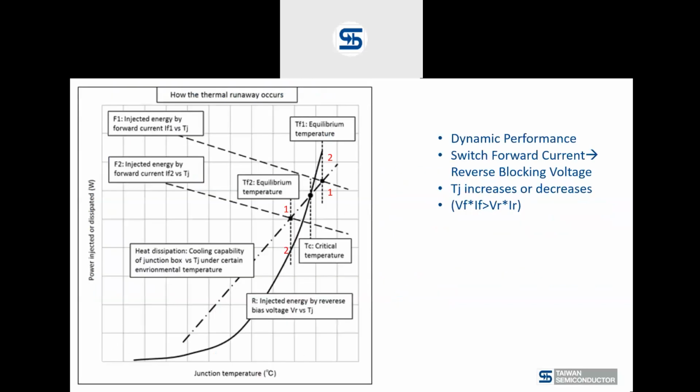This is a slide which I took from the IEC norms on photovoltaic junction boxes on thermal runaway, and it just explains the phenomenon. The same happens when you're using a Schottky as an OR-ing diode, or actually in other applications. And if you're using it in a power supply, it just happens every 5 microseconds or 20 microseconds, depending on if you're switching at 200 or 50 kilohertz or something like that.